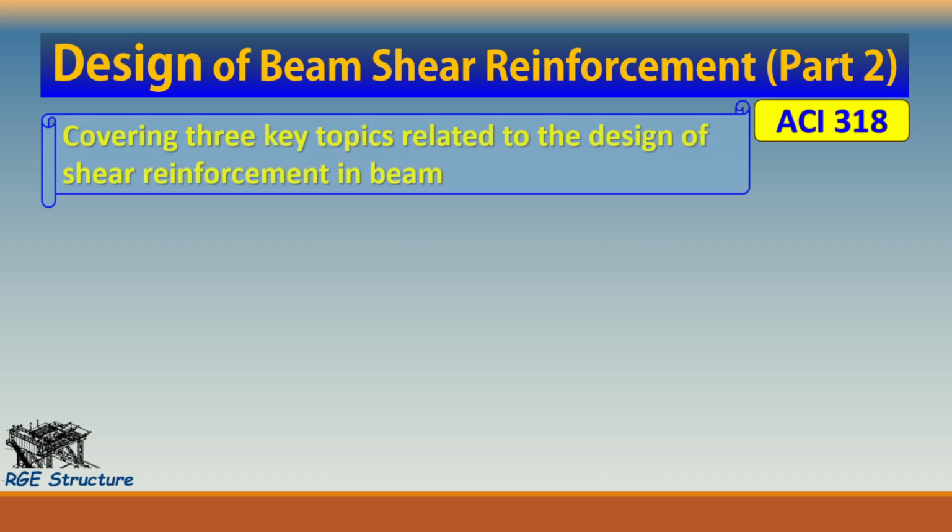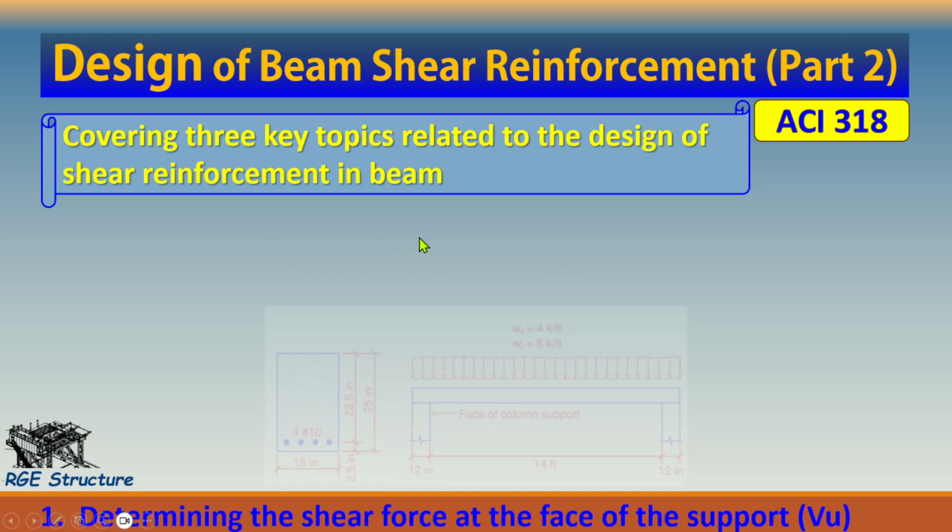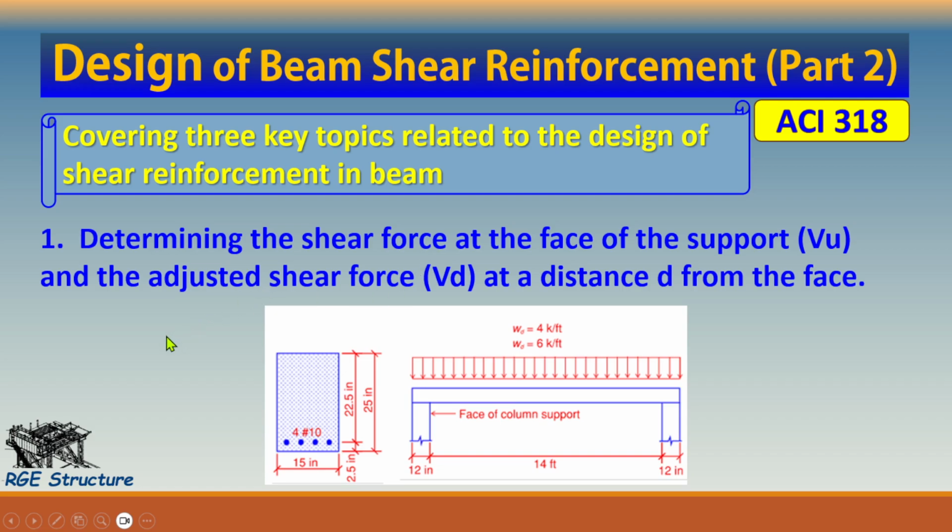Welcome to my channel. In today's video, we will walk through another sample problem on how to design the beam shear reinforcement, part 2. In our calculation, we are covering three key topics related to the design of shear reinforcement in beams. The first one is determining the shear force at the face of the support, Vu, and the adjusted shear force, Vd, at the distance d from the face of the support.